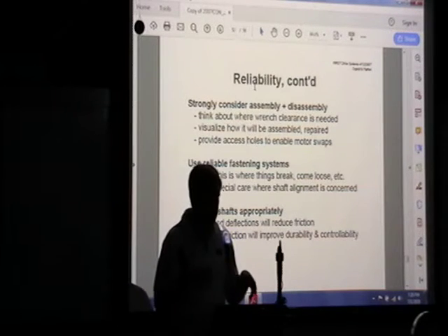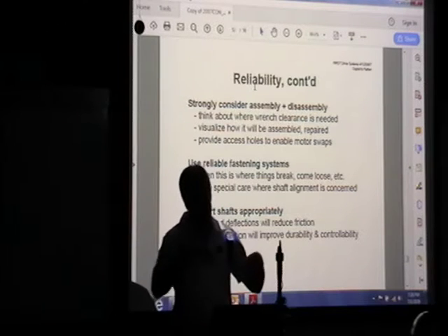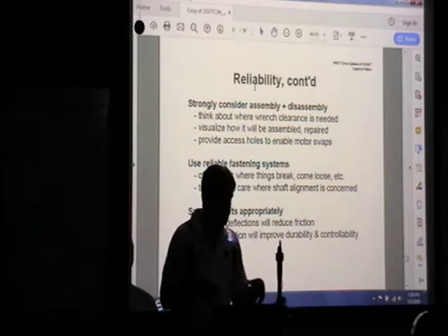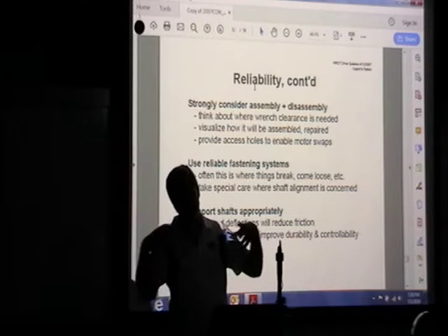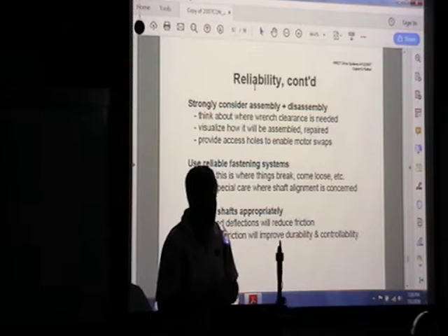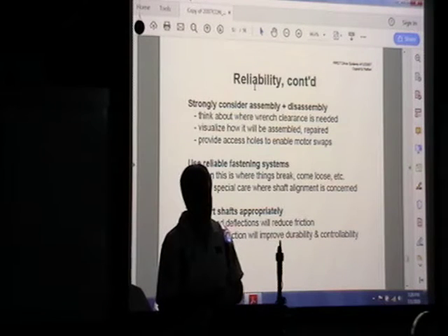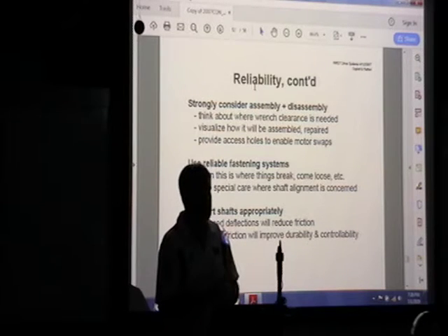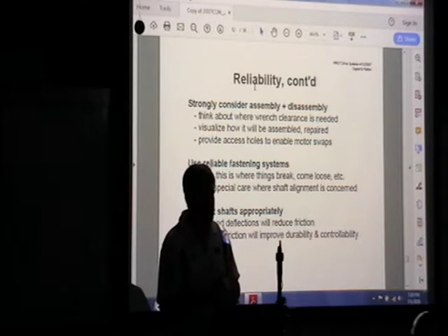Obviously, if you have to put a gear set together and then you put something around it that builds it out further, and you can't get to that gear set to fix it, you have to take the whole assembly out and the whole sub-assembly apart to get down into that gear set. So try to apply some thought process to how you put these things together, maybe have some access holes, something else to help you repair the things that are in there.